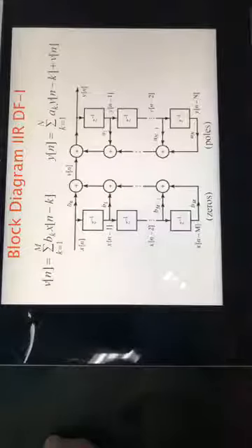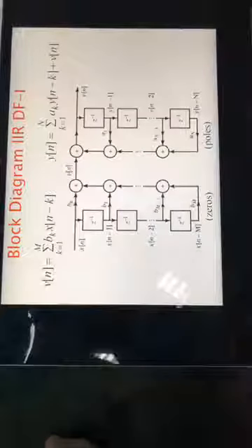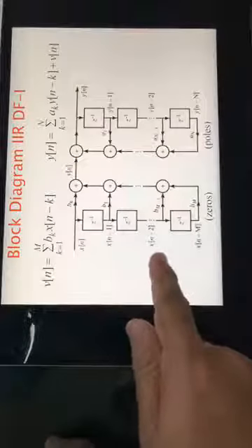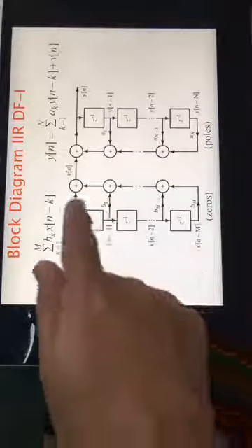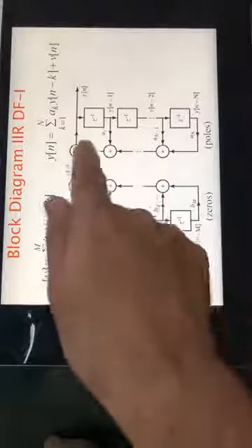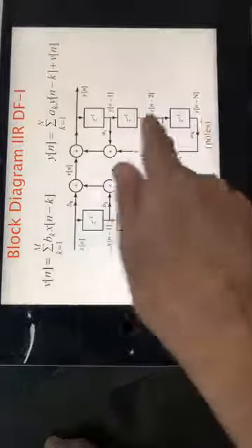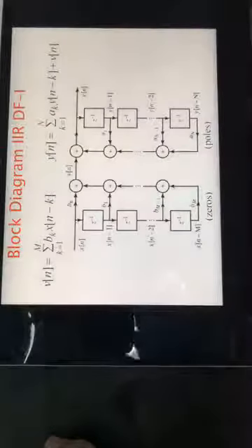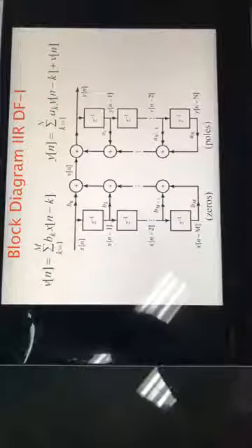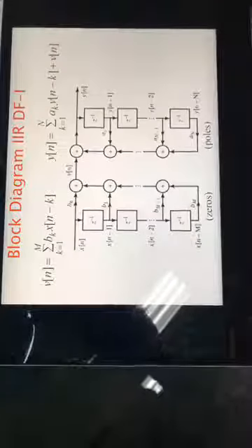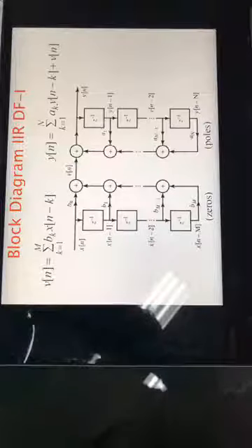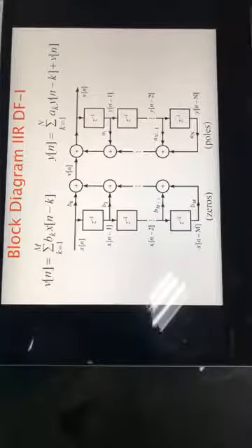This is direct form 1, which Dr. Ali has covered, that you have x of n, x of n minus 1. You do the multiplications, add them together. This is v[n], and then you do all the previous samples of y, add them up together to get y of n. By looking at the expression, you can actually develop this structure or implementation.